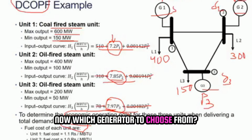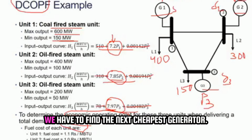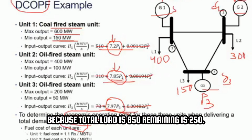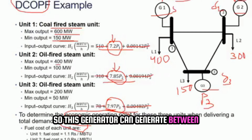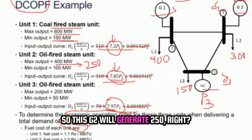Now which generator to choose? Exactly, good. We have to find the next cheapest generator, and the next cheapest generator here is P2. So we will pick this generator. Because total load is 850, the remaining is 250, so this generator G2 will generate 250, right? And with this the load is balanced.